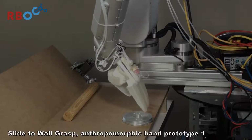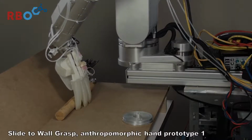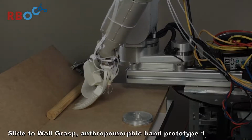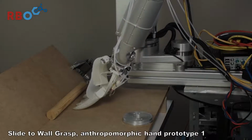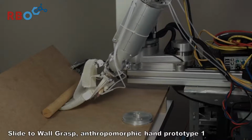Here is an example of an even more complex exploitation scheme. The RBO anthropomorphic hand first pushes the object towards a corner, where it uses a wall constraint to slide its fingers underneath it. Finger flexing and wrist rotation complete the grasp.